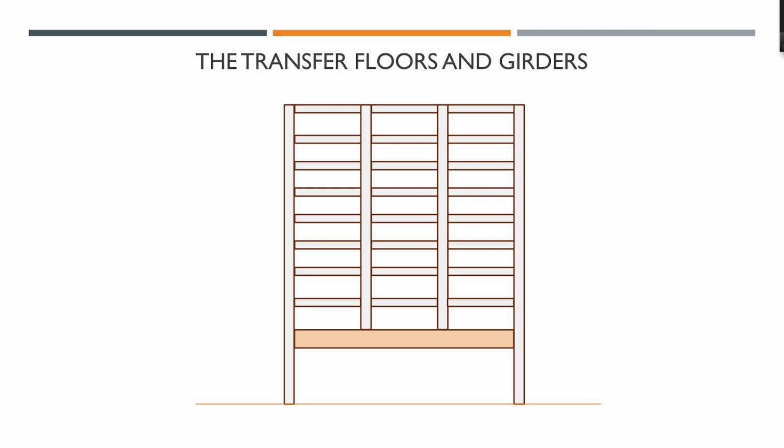So sometimes the load path will be interrupted. Like I said, in multi-use buildings, there is an entranceway. Nobody likes to have a column there. So columns are coming from the top, and suddenly columns will be stopped. So all the gravity load coming from the floor to the column down here now cannot go further. So you have to now transfer it to others.